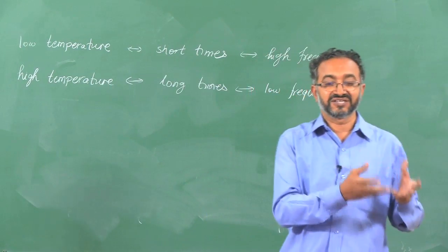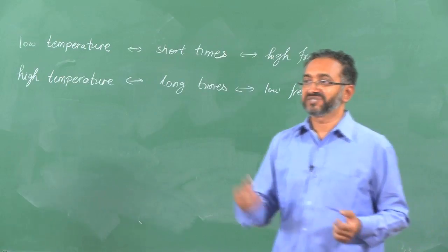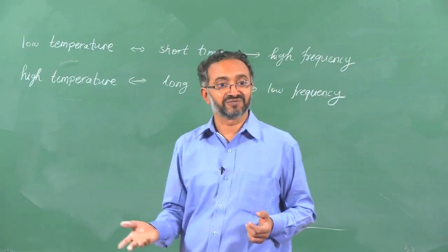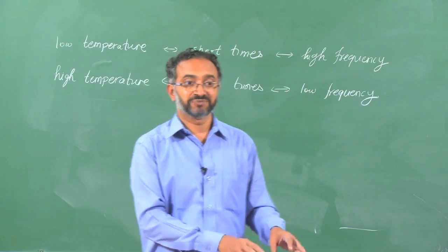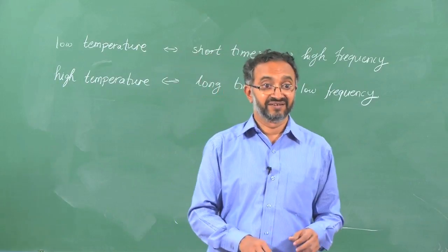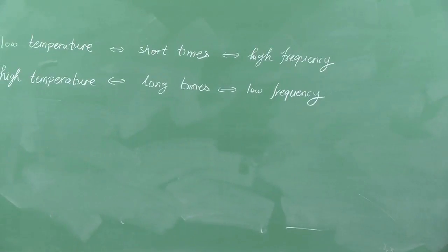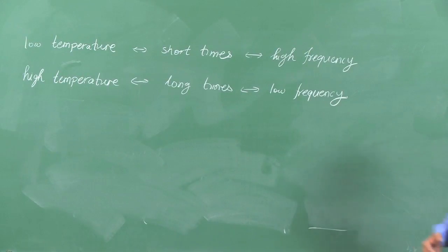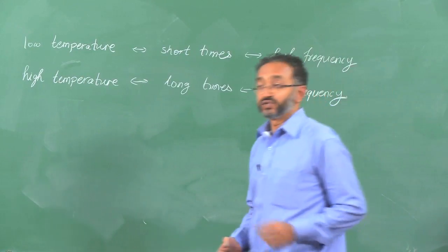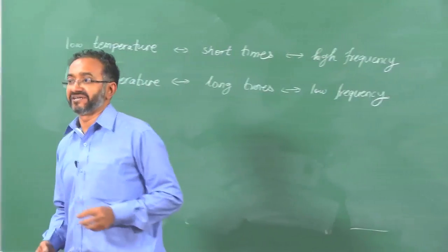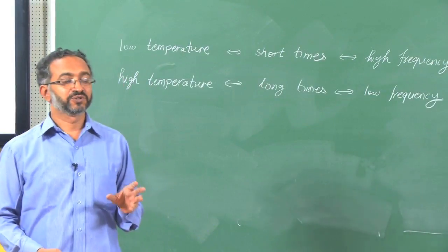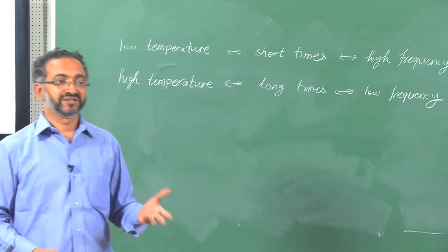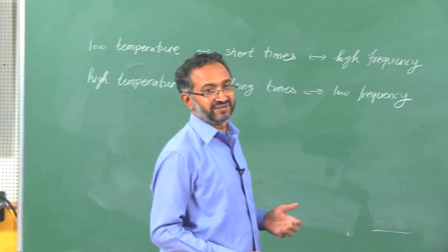Clearly, the relaxation processes which are present are going to be different. When crystals are there, there will be one set of relaxation processes, and when the melt is there it is another set of relaxation processes. So you would expect that this kind of process will fail. Empirically, when you do time temperature superposition, it will not work, because the underlying set of relaxation processes themselves have changed. For a material which is structurally changing, time temperature superposition would not be expected to be valid.